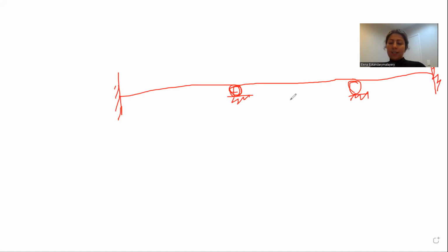Okay, let's say we have this beam, which is obviously indeterminate. We have 3, 1, 1, and 3, which comes to 8 support reactions, and we only need 3. So we have 5 degrees of redundancy. So it is indeterminate and stable. So in order to analyze it, we need to use a method that we don't know yet.